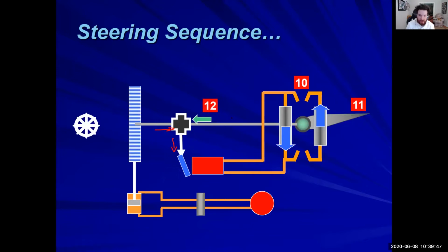That rudder is now in position, and it's giving input back into the differential. It's spinning that yoke back into a neutral position and moves that tilt box back into its 0 stroke. Now we are ready for our next input.